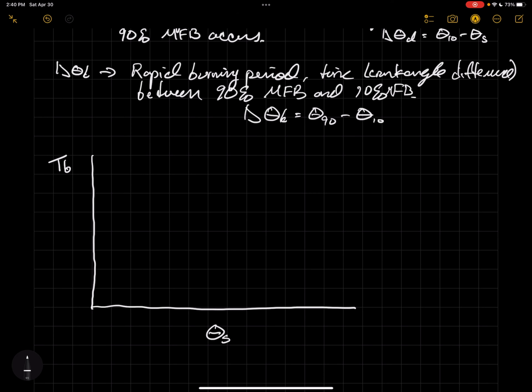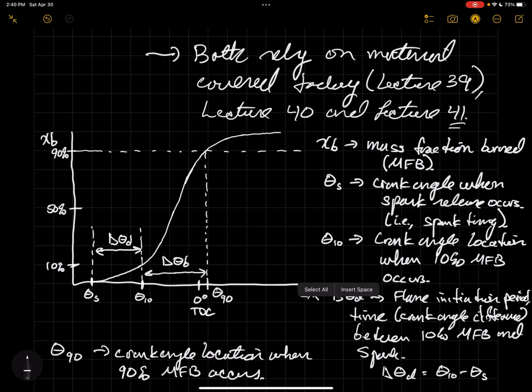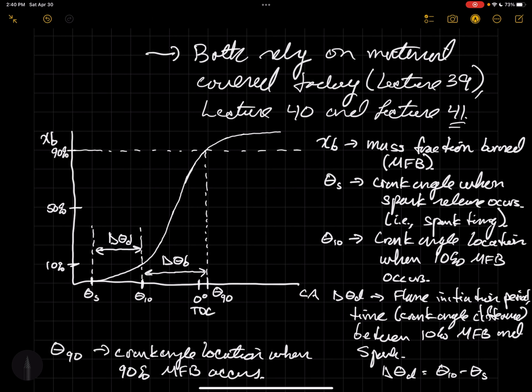Okay, so be careful here. This x-axis is not crank angle degrees in the sense of how it is up here with the mass fraction burn curve, where I have 0 degrees, which is top dead center, right, indicating that the piston is moving through this range. In this plot, the piston is moving through the compression stroke, reaches top dead center, reverses direction, and then moves down toward the expansion stroke, right? And so this is the engine crank angle for one given cycle.